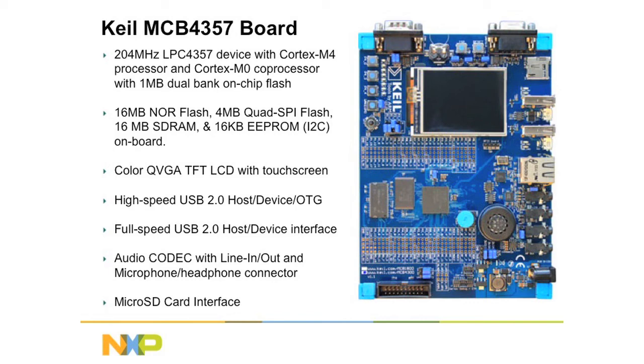The board has a bunch of memory on board. For this particular application, we're running it out of the Quad SPI flash. So we have a peripheral in this part called Spiffy that allows you to execute code from SPI flash, which is really nice. The board has a color LCD display, which we will be using.